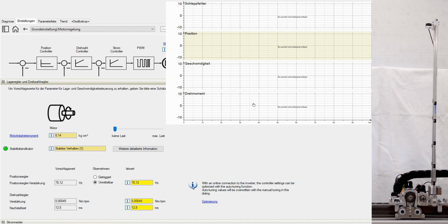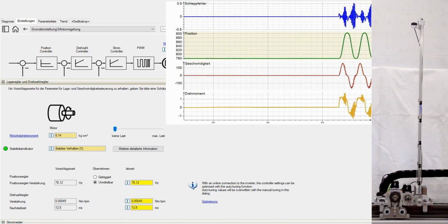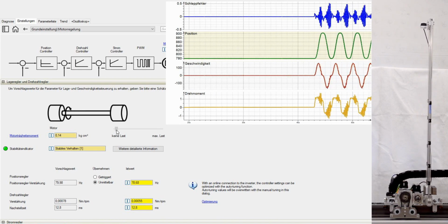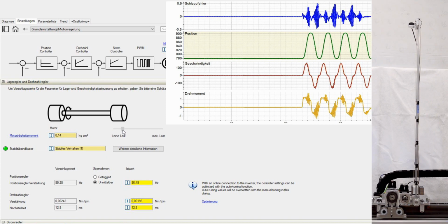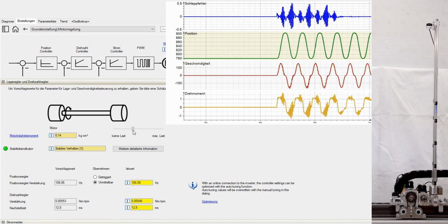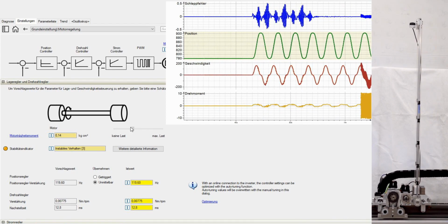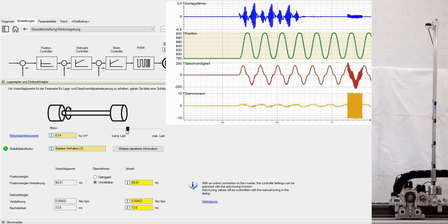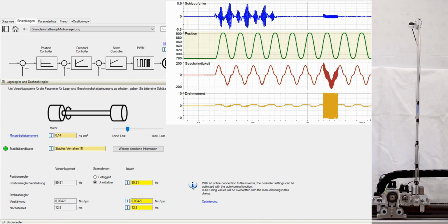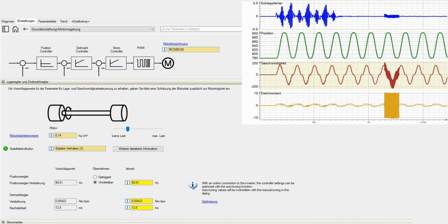As soon as the movement is started, the trace starts recording. After that, you can start moving the slider slowly until an instability is reached. This can generally be seen on the indicator and in the trace, but can also be heard. The slider should then be reduced to about half again. This position then represents a good slider optimization. The resulting controller parameters can then be read from the actual values. After successful setting, the movement can now be ended, and if wished, the trace can be viewed in more detail.